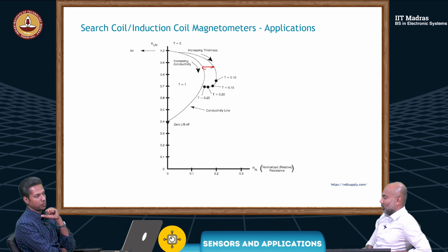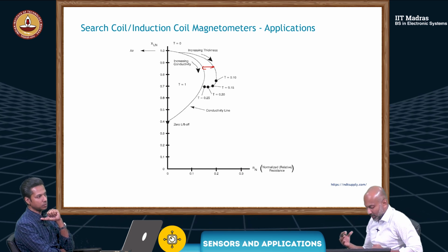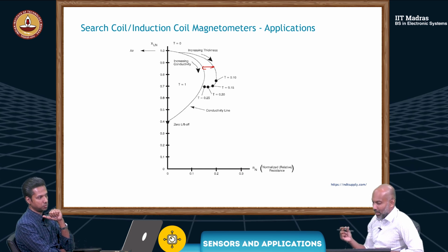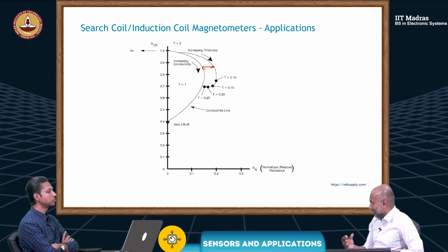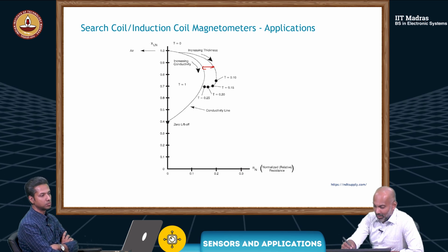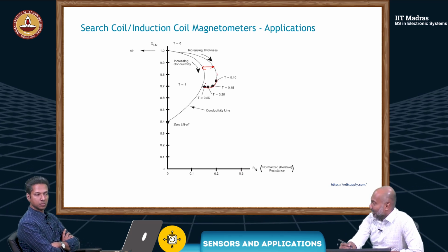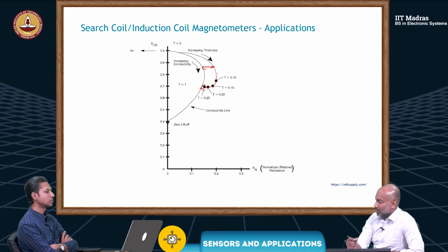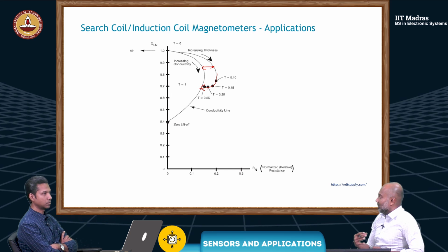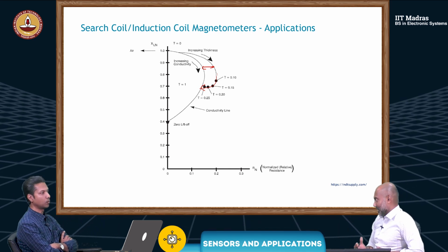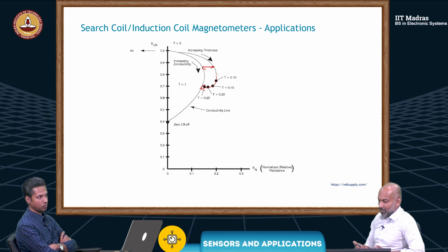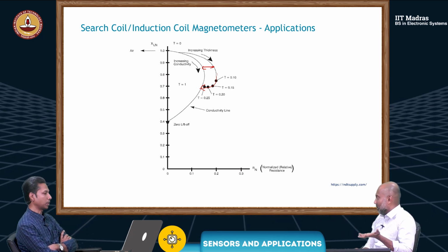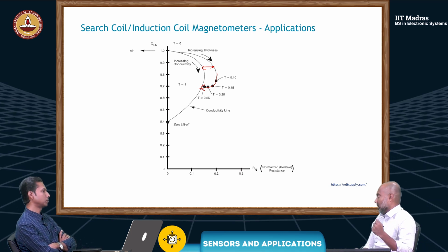Correct. So you'll probably see an increase in the resistor component when it's thinner. Now, as you get thicker and thicker, it kind of comes back to the curve until your depth of penetration is smaller than the actual material thickness. So you can also measure the thickness of materials using this method.